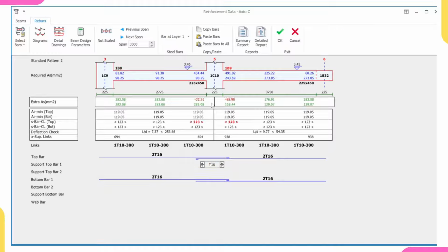Look, it is failing here, meaning that it is failing in bending, like in moments. That means I need to provide more reinforcement to counter the moment acting on this beam, because you know the bending moment diagram is like this, then it will go up, come down again, then terminate at 0. So to counter it, you increase the reinforcement. You keep on increasing it till it passes. Let's go over to the bending moment diagram.